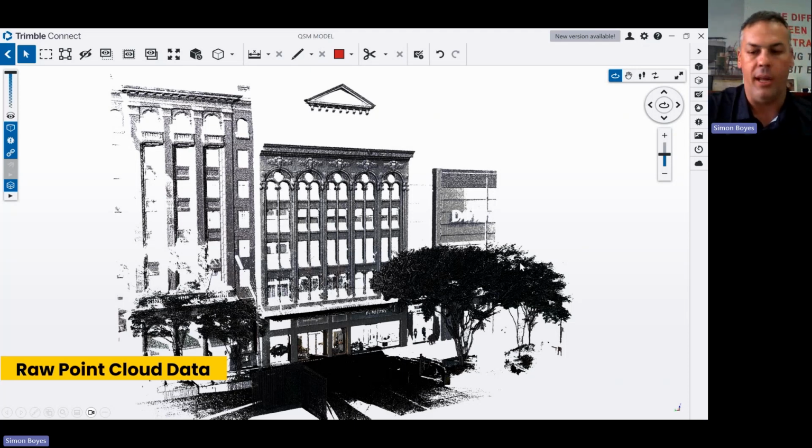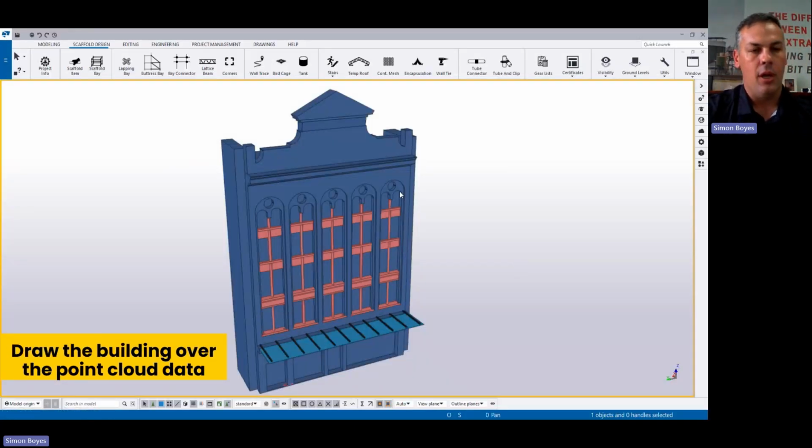Once we create that 3D model here, it's accurate up to that particular scanner's limits. I think the accuracy is about 3 millimeters over 60 meters. So depending on which scanner you use determines how accurate they are and what distance they can shoot. And to be honest, you can go and buy scanners that are $100,000, $200,000. But for what we're doing in the scaffold space, I don't think it's really necessary, because you just might need to do more scans from more locations to get that accuracy. And that's why I think that entry level scanner is a great option.